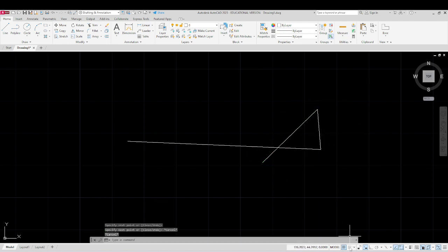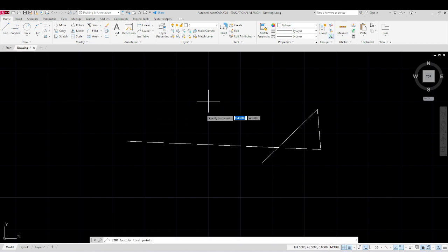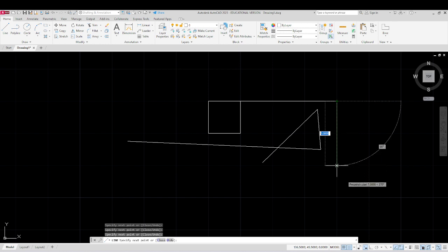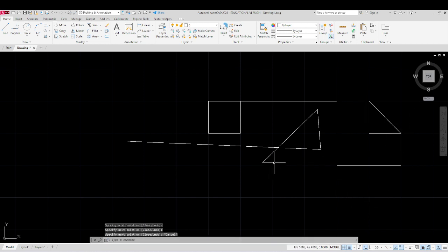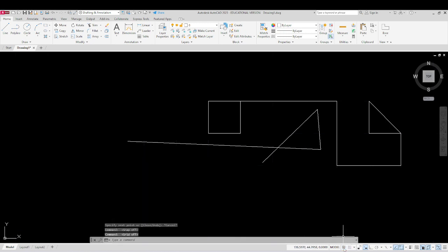In this way, using the snap mode, you'll be able to select a point only on the intersection of the grids. You cannot select a point in between. So it is easy to draw vertical and horizontal lines using grid mode, but the problem is you cannot select any point which is not on the intersection of the grids. So we also prefer to turn this off, so we will be turning this off. Now the next symbol, we will not be requiring, so we will not study this.